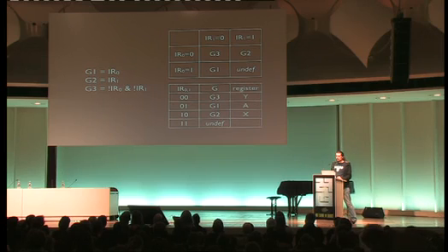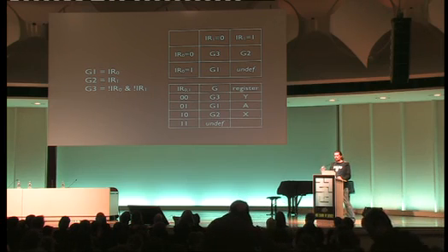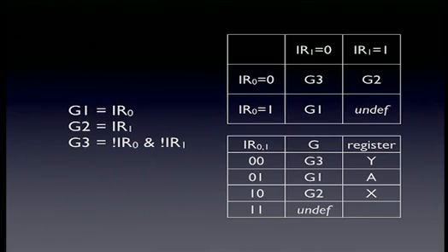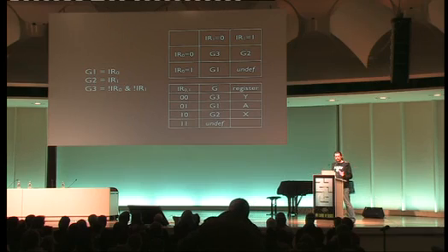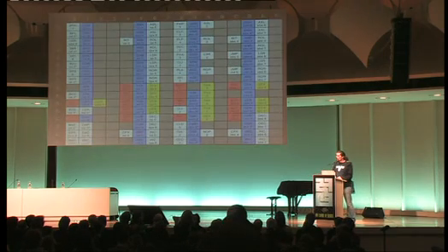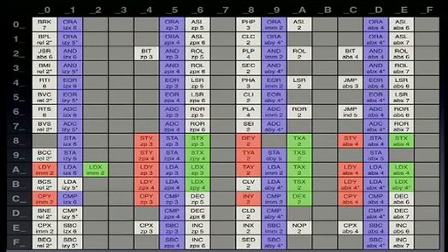Or how you can interpret this is that G actually encodes which register we're working on. So the lowest 2 bits say is it A, is it X, is it Y, for certain instructions. Others don't care about registers, so they don't care about the G, so it's a don't care, an X there. And you can see this in the opcode table. The columns 0, 4, 8, C are the ones that mostly deal with Y. All the ones that deal with Y are typically in those. And then the next column is all about A, and the other one is all about X. So it's all about the lowest 2 bits.